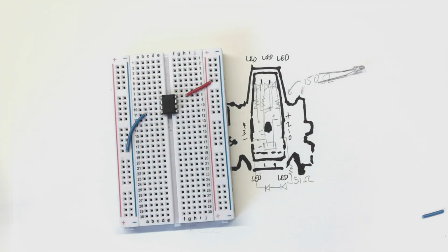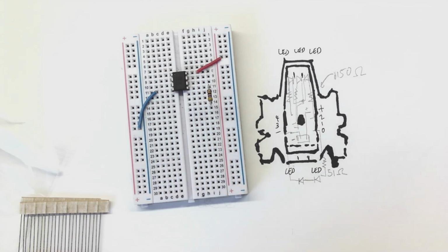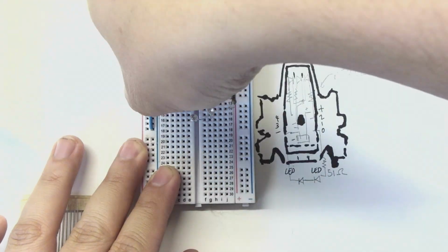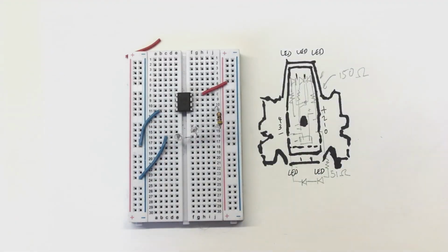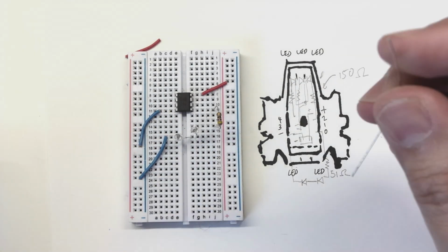So I've connected the left blue negative rail to row 11, which is also where the negative pin is touching on the AT-Tiny 85, and I've done something similar for the positive pin and the positive rail. Next, I connect each of the LEDs and the resistors to the pins on the integrated circuit, in other words the AT-Tiny 85, and then to the common ground, which is represented by those blue rails.